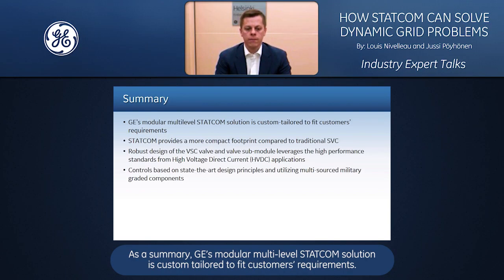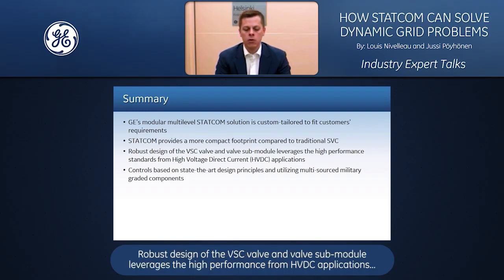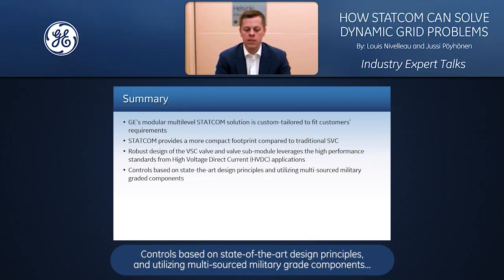As a summary, GE's modular multi-level Statcom solution is custom-tailored to fit customers' requirements. Statcom provides a more compact footprint compared to traditional SVCs. Robust design of the VSC valve and valve submodule leverages the high performance from HVDC applications. Controls are based on state-of-the-art design principles and utilize multi-sourced military-grade components.